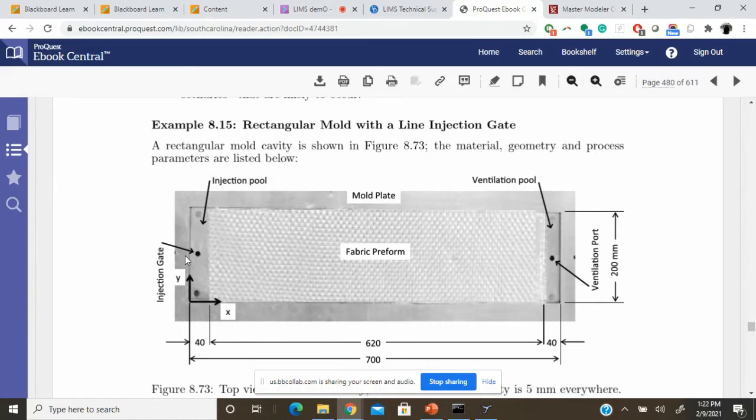But in this case, we already have this model saved from the appendix C files that we downloaded. We would go over the meshing in the following demo, but in this case, to get yourself familiarized with race tracking, all we are going to do is use the existing model with the predetermined nodes and elements, and run the simulations to see the mold filling time.